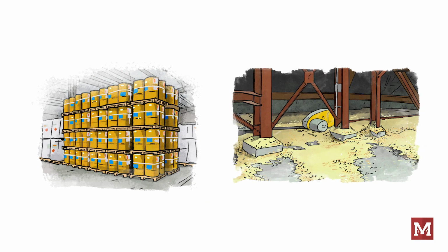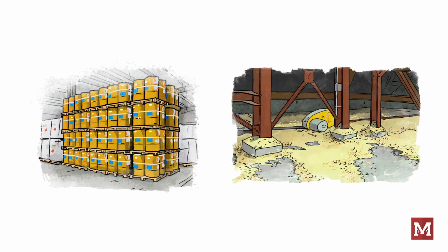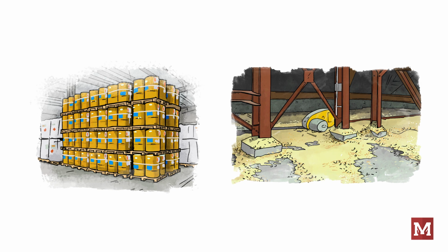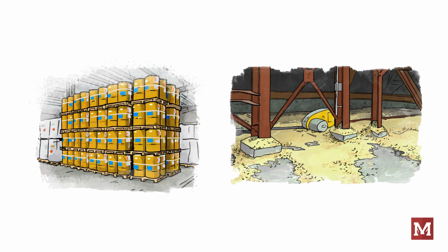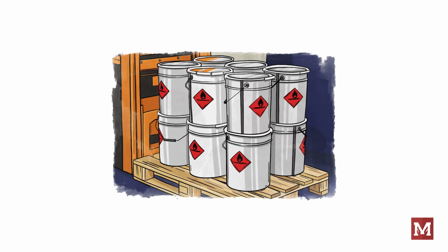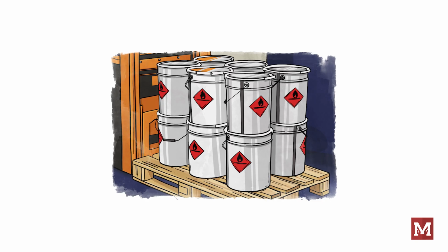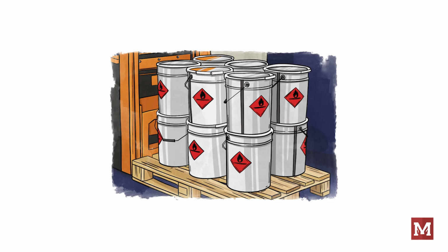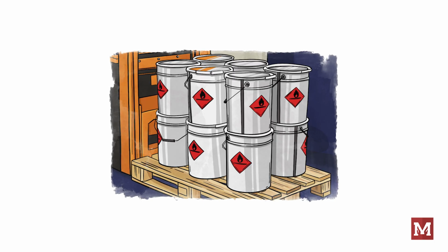A small pile of wood dust that missed a trash can might not present much of a hazard now. However, if not managed in a timely manner, the wood dust can accumulate over time, presenting a larger fire hazard, and then potentially being suspended in air, which can pose a tremendous explosive hazard. Some materials, including gases, liquids, and solids, have properties that we deem hazardous. In addition to the combustible and flammable hazards, we will see that there are other hazards where accidental exposure or abnormal conditions could significantly threaten the occupants and property.